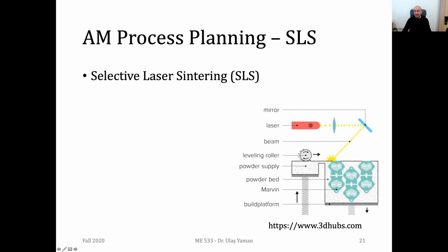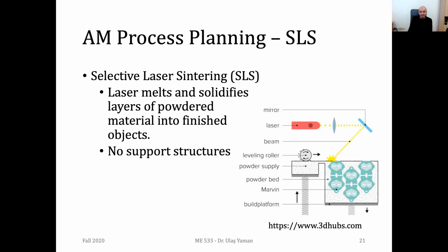And this one, as you see, is going to the right, and it's also rotating. And with the help of the laser, these powders are sintered together. And the remaining powder inside this bed is actually not sintered, but probably has undergone some temperature increase. You may use some of the powders inside the bed, but not completely. There are different recycling systems depending on your equipment. You may try to recycle some of the powders inside the bed, but the most important thing is that you don't need to have special support structures in selective laser sintering systems.